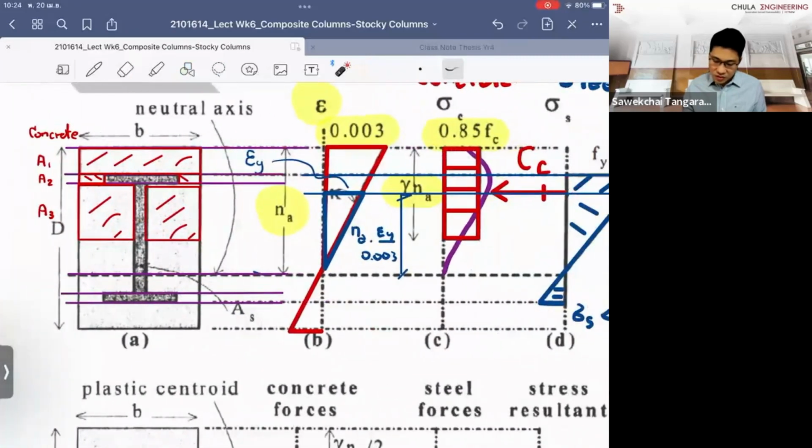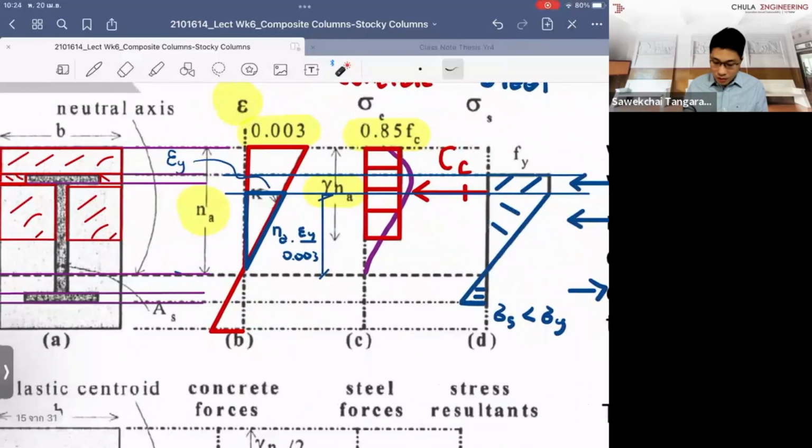So when you have the stress times the area, you get the compression force, but you have three different values of the areas that you use, and that can be calculated for the sum of the compression stress, so the compression force of the concrete. And for the steel, it's even more difficult because you have the non-constant stress developed in the steel, and this one is in triangles.